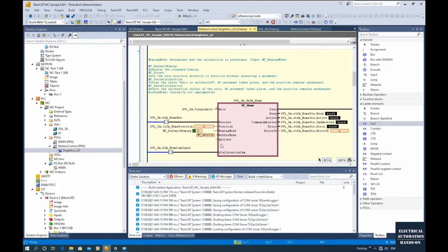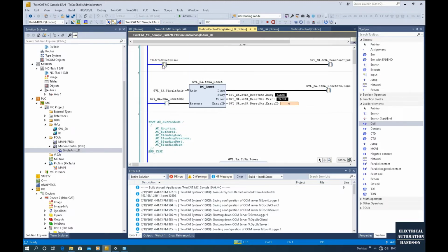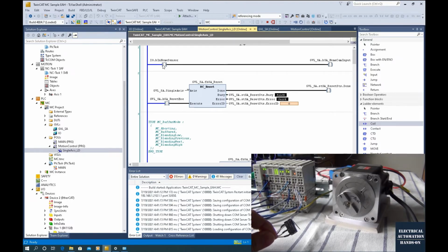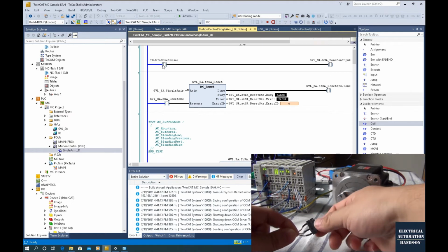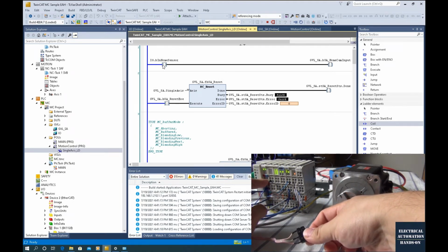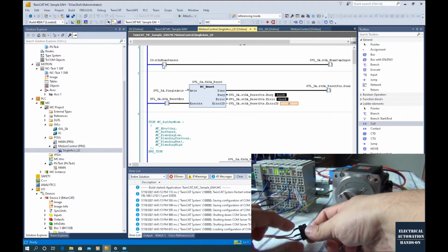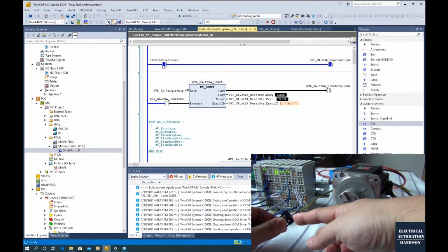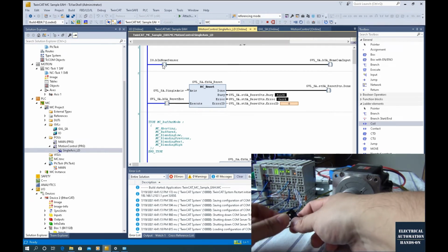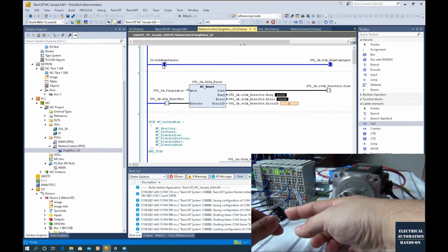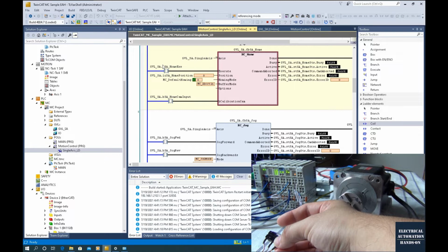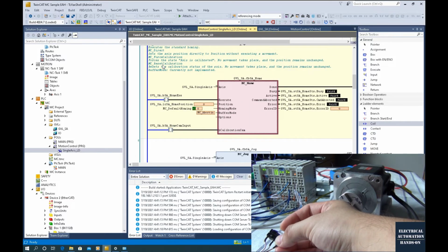Okay, so quickly review our hardware. And also, let's check out this home sensor and see if this home sensor is working properly. Okay, now I'm using this simple switch on and off. I'm connecting that switch to this first input terminal. It has 8 channels. I'm connecting to the first channel. So if I turn it on, we can see the first channel turn on here. It will be used for this home sensor, this function block, the calibration CAM.